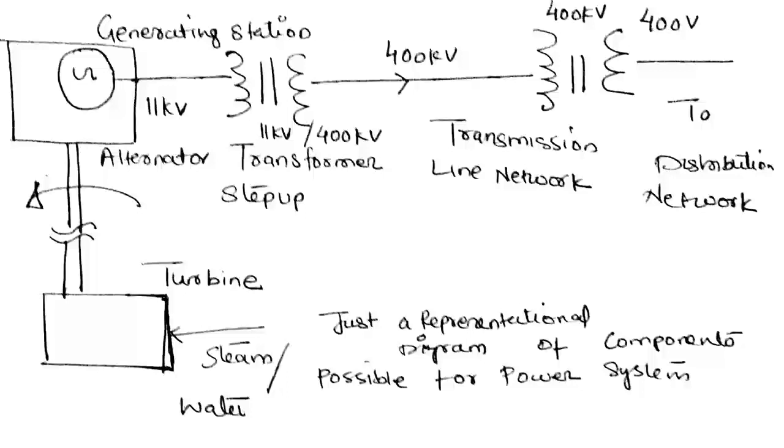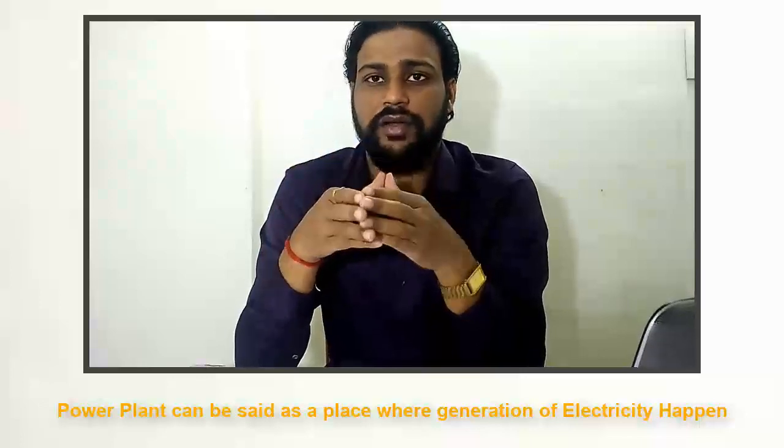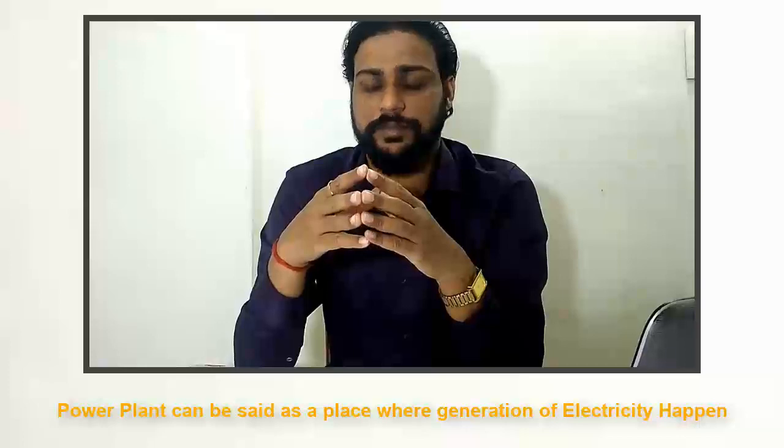There would be substations which step down the voltage nearby the distribution area, and a different voltage could be given to the industries. The voltage used for distribution could be close to 400 volt, that is a line to line voltage. If you are familiar with electrical engineering, a line to line voltage is between two lines, and the line to neutral voltage is between the line and the neutral, which is connected to the earth. The line to neutral voltage will be 230 volt. That is the voltage which is coming to your house for electrification purpose.